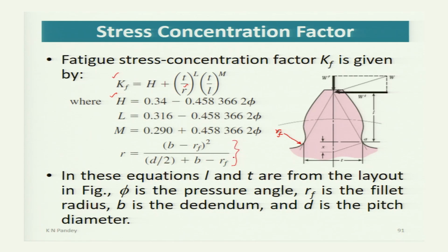So, knowing this r, knowing the pressure angle phi, knowing the thickness of the tooth at the fillet, this is the t, knowing the l, this height of the gear tooth from small a to the vector Wt, the transmitted load, and small a is the point where a line drawn from the point of application of Wt is tangent on this fillet.